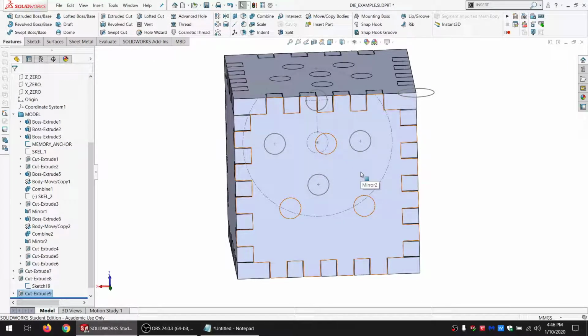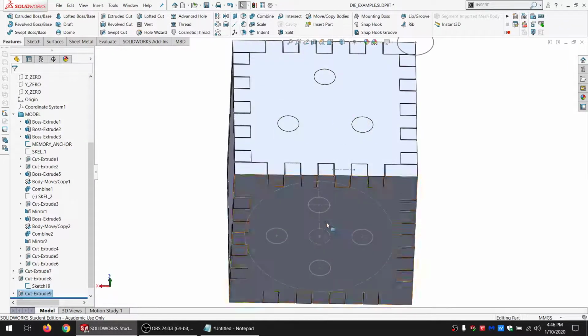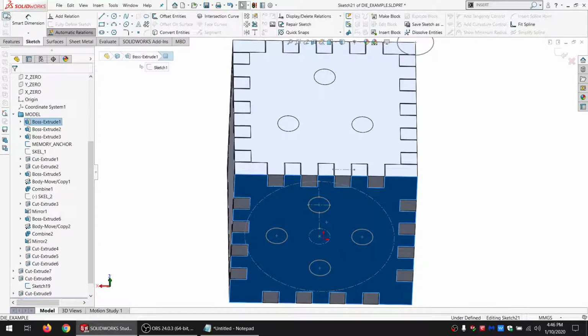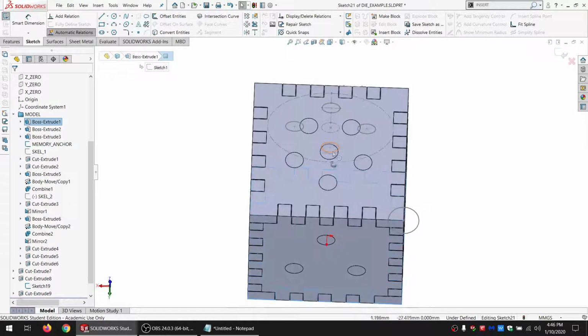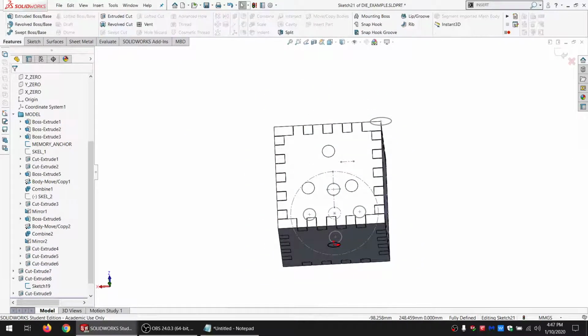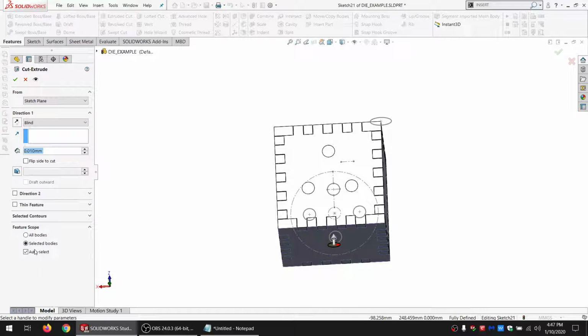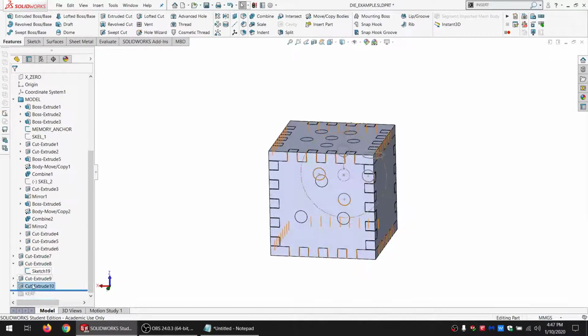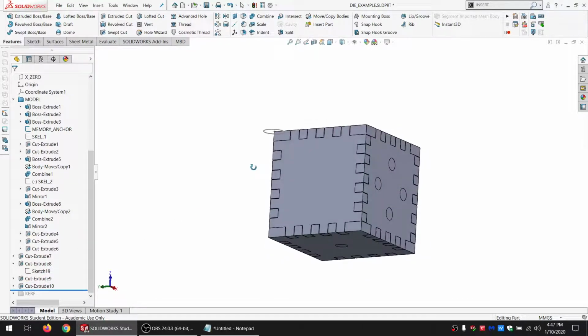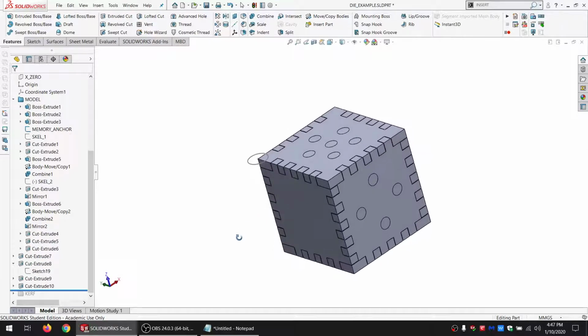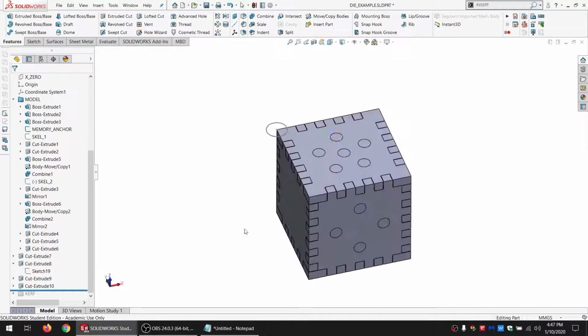So it's the side opposite 6. That is 1. That's nice and easy because we can just convert the center. And extrude cut. And I only want to be on that body. And not that it would be on any other body anyway, but I like to do that just as good practice so that I don't forget, basically. All right, so if that's 6 and that's 4, then this will be 2.